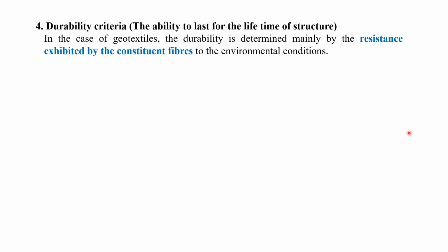Now we can see the durability criteria, the ability to last for the lifetime of the structure. So the geotextile should also meet the durability criteria. In case of geotextile, the durability is determined mainly by the resistance exerted by the constituent fiber to the environmental conditions. That means whatever fibers we have used in manufacturing the geotextile sheet should be durable and should have the capability to resist or bear the environmental problems.